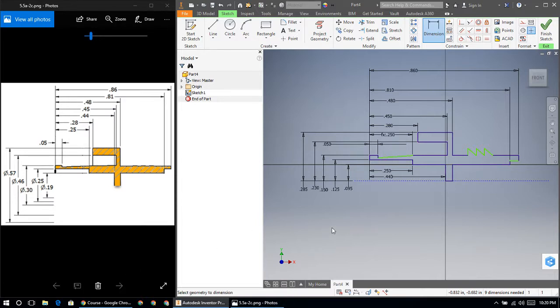And we're getting pretty blue here. Looks like this line here is not right, so again I'm going to horizontally constrain that point to match this one because those go together. That took care of it. Not sure why we're not green here. Oh, I know why. We haven't told it the size of this yet.